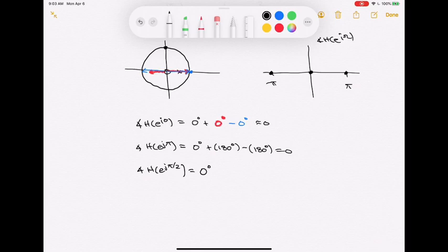Now I have to figure out the angle from the 0 to this point. This one I can do. The 0 pointing up to that point has an angle that is 90 degrees. So in this particular case, I'm going to add in 90 degrees. And then I need to subtract off the angle that is made from the pole to that frequency of interest. Now you could go through the geometry in that particular case.